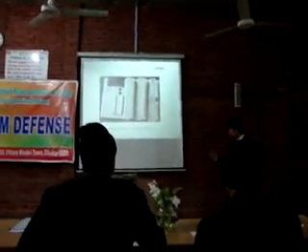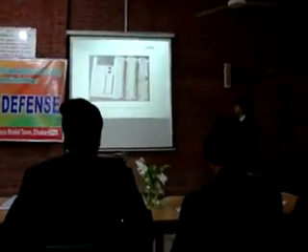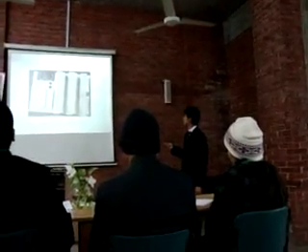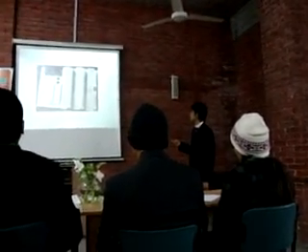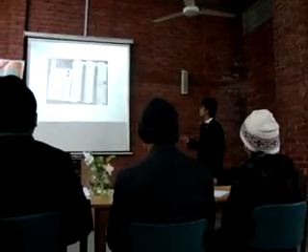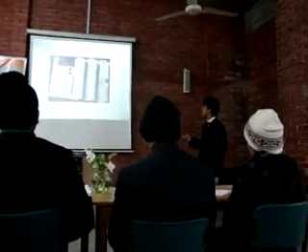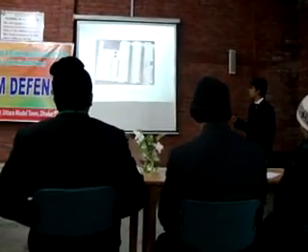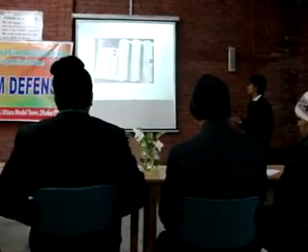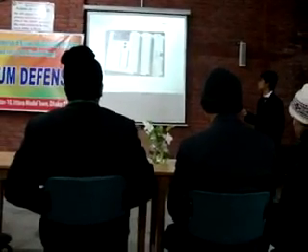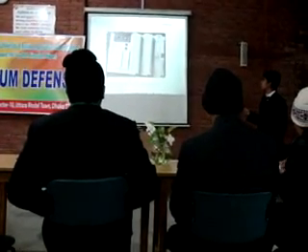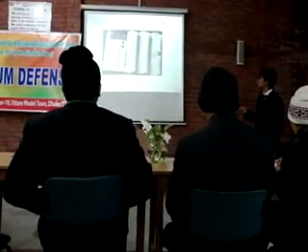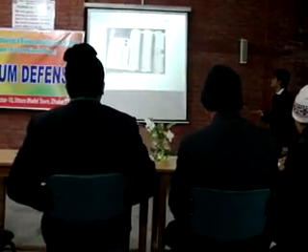This is the PLC used in Niagara Textile. This PLC has the input module, output module, and analog output. These ports are analog output, and this is the PCMCIA card, generally called EPROM, and there is the TER port. This TER port is used to connect to a PC for downloading programs to the PLC. And this is the auxiliary port, with the same ports. And here are the indicators. Different conditions will show here. There is a battery indicator, run indicator, error indicator, and input-output indicator.